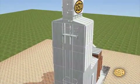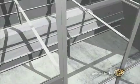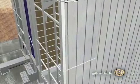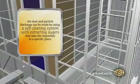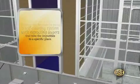Recirculation chamber. Located between the drying column and the external environment, the recirculation chamber is a protected area that allows the hot air to circulate after passing through the grain. This enables the reuse of the air, isolation from external factors such as the cold and rain, particle retention, and easier operation. Due to the low speed at which the air leaves the grain column, the particles fall into the dryer, making the installation of filters unnecessary. As a result, the process dryer always operates at maximum drying capacity without waste.